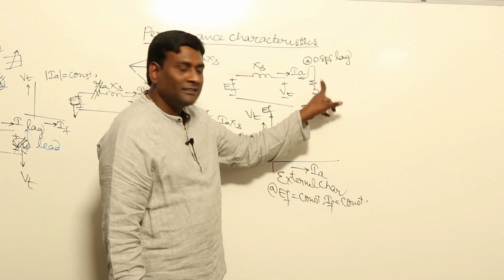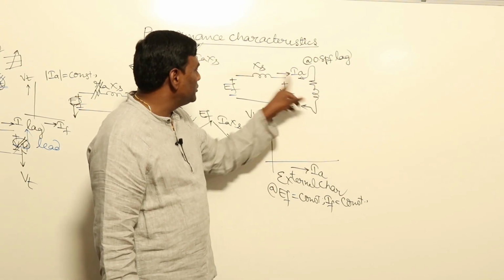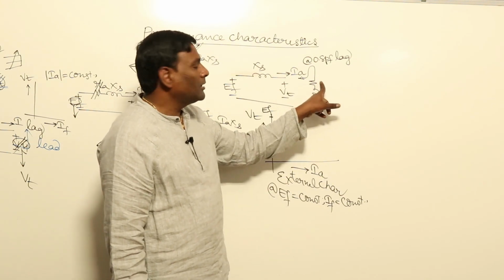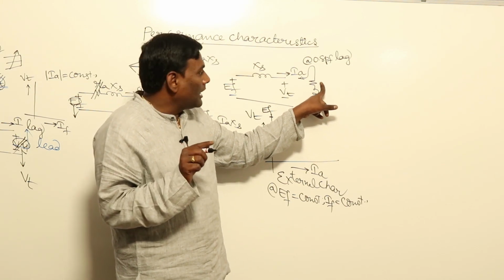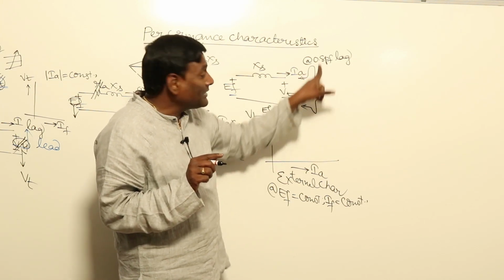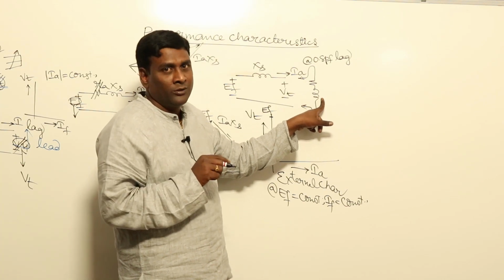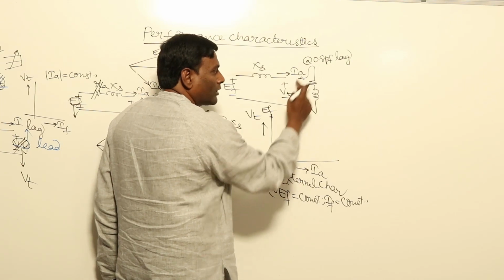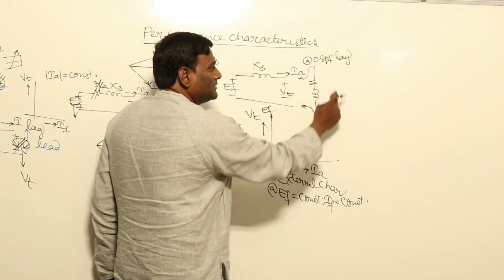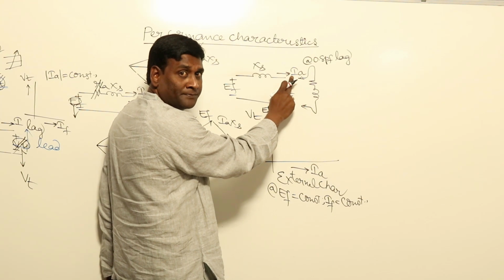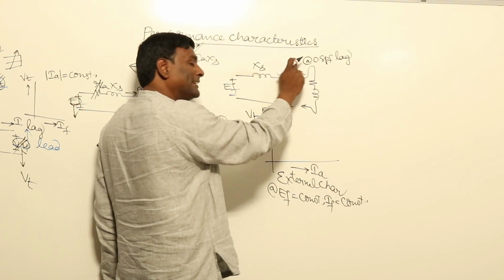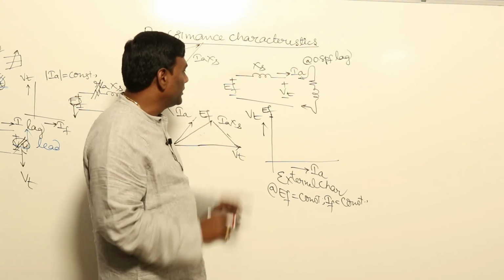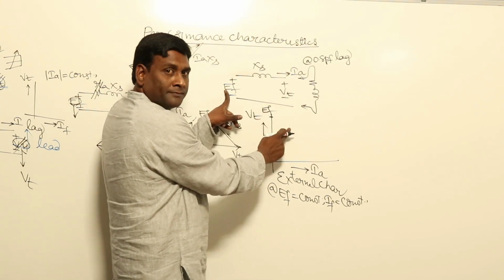Okay, this resistance is infinite, X is infinite, such that IA is 0, EF is nothing but VT. Now for example, if resistance is reduced, and in order to maintain 0.8 power factor, reactance is reduced, then what will happen? Lagging current will increase, because total impedance will be reduced. So total impedance is reduced means that magnitude of IA will increase. So if magnitude of IA increases at lagging conditions, voltage regulation should be positive, means that VT should be reduced.